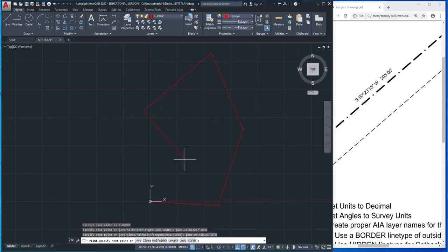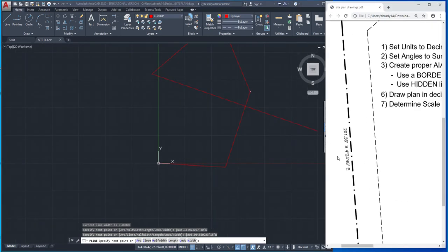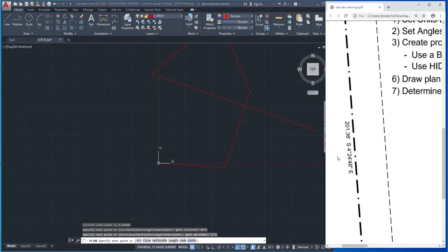Enter. Looks pretty good. All right, here's the most tempting decision ever in AutoCAD, right? It's very tempting to say, hey, guess what? I only have one line left, and I know that if I come down here and I just hit the endpoint, that it will close it right up, but we are never going to do that, okay? We're never going to do that, because when you're working in the real world, there is always the potential that there could have been a mistake when you were given some information, right?